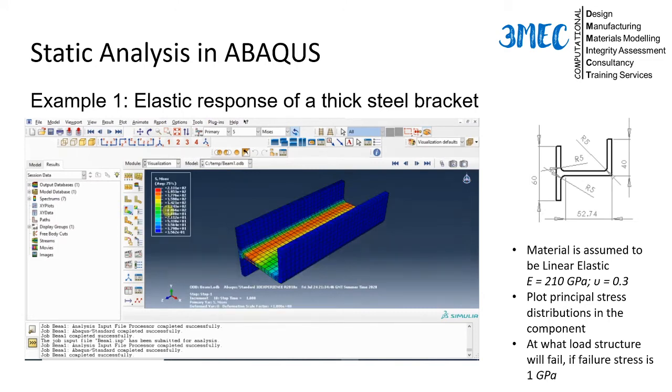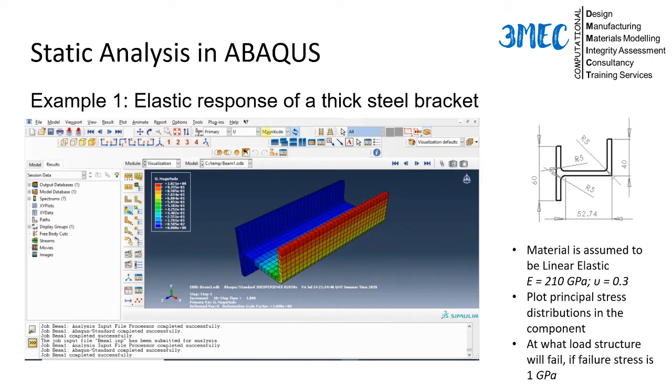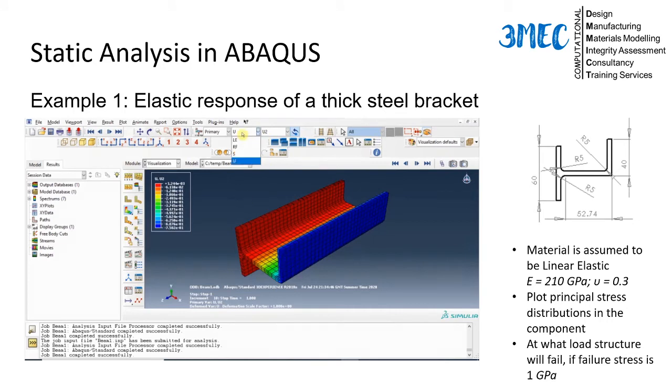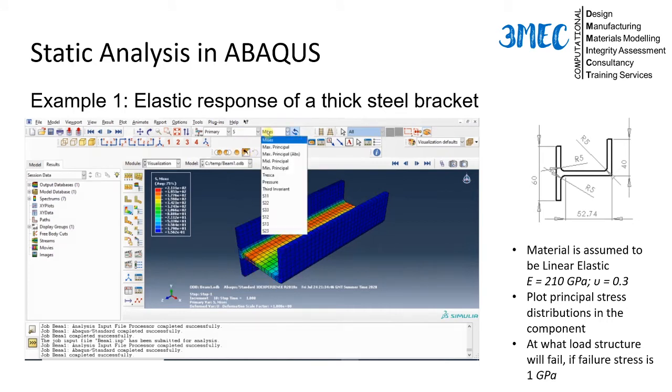So now I go to the results. When I press this, now my stress should be higher, and you can see now it's 213 megapascals. So still 1/4 of 1 gigapascal of failure stress. So you can play around with different variables here. Here I'm trying to plot the displacement to see everything is consistent with the boundary conditions, which looks okay to me. Stress wise, this is Mises.